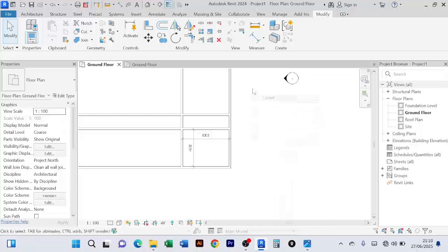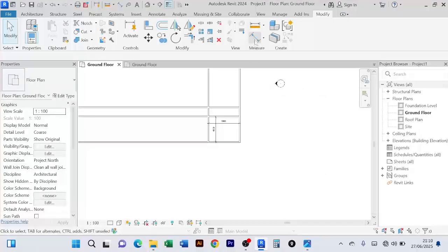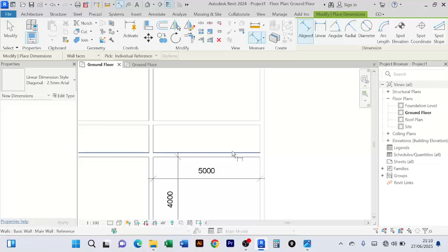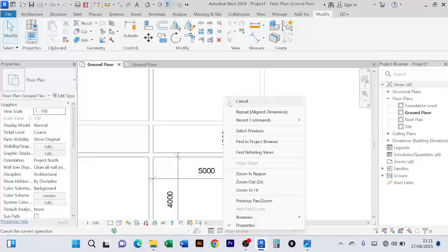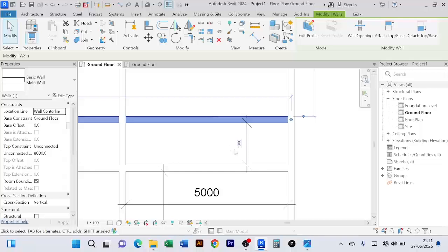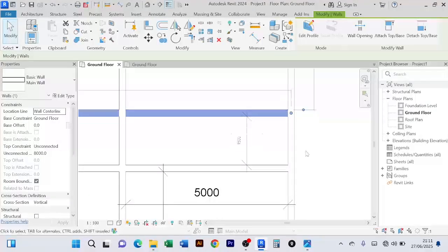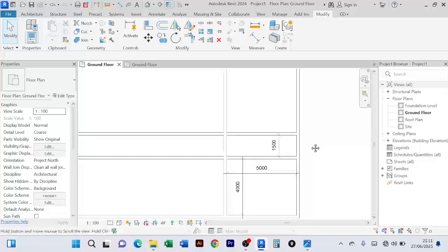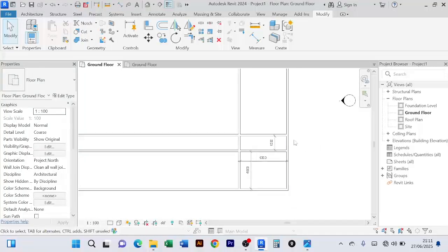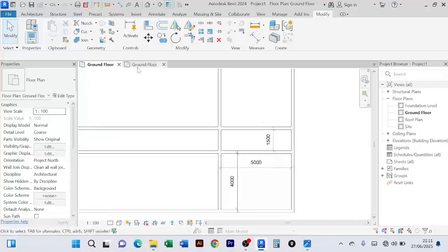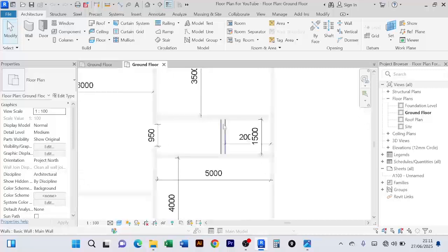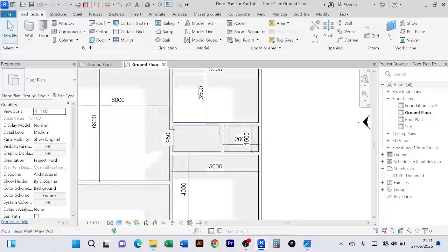After offsetting, you escape. Then you go to your line dimension tool, the DI. You measure from here to there, and you see it is 1.3. You click on the new wall, you click on the measurement, you make sure it is 1.5, just like that, and we proceed. We have created this. However, if you see here, there's some kind of partition in the middle here.